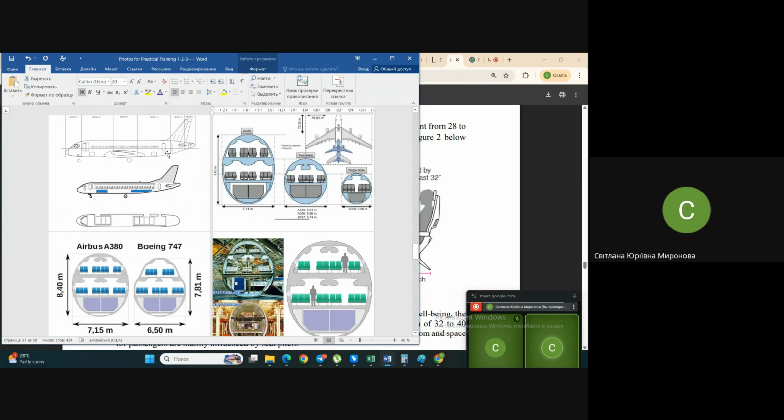That is checked during the landing gear design, where to place the main and nose legs. I hope we're all going to use the so-called three-wheeled scheme, the conventional one, and where to place the main landing gear with respect to the fuselage. It's also a very important moment because if you place it wrong, as I already said, if it is too close to the nose, during takeoff the airplane may just kick, forgive me, the airfield by its aft fuselage.